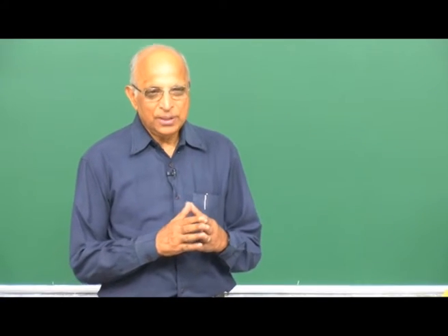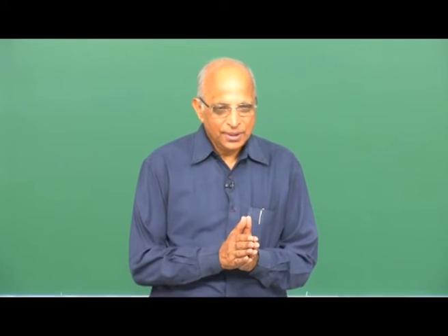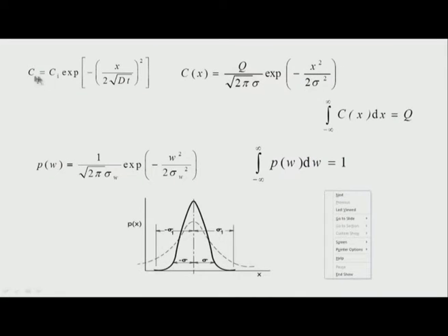Morning. In the last class we looked at the solution for the dispersion equation, namely what we called the diffusion equation. We found that the solution gives the concentration at any distance away from the source, where at the source you have a concentration, let us say Ci kilograms per meter cube, at a distance x from the source and at a time t